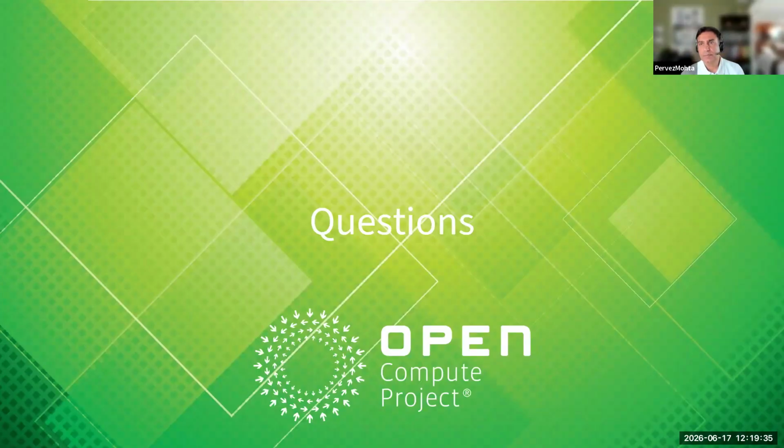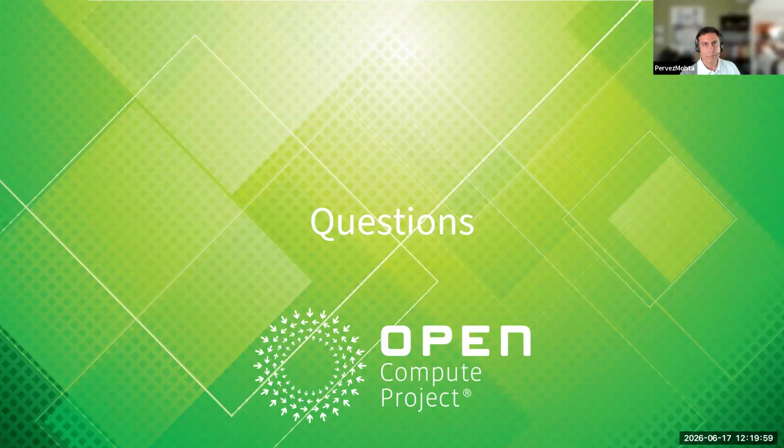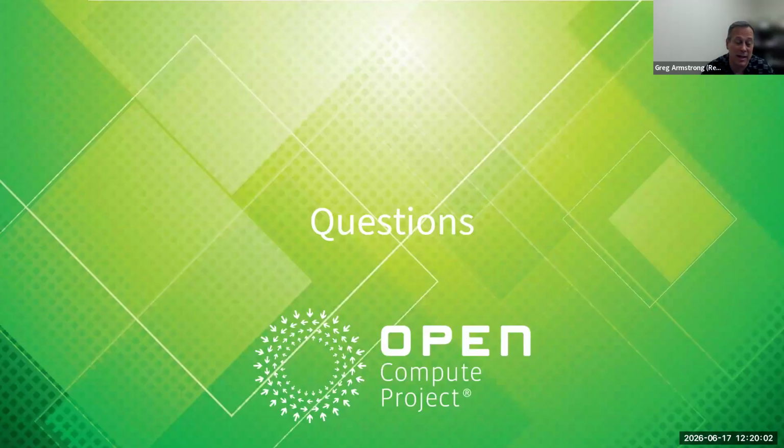Got it. So in a way, I think that's why 10 megahertz became popular. But we've seen 25 megahertz used, especially in some backplane applications. And maybe there'll be a switch to 25 meg because it's probably a more common clock frequency used in cloud servers, or it may even go to 100 megahertz. And as was highlighted, why not start modulating the PCIe 100 megahertz clock itself? We dabbled with that a few years back. But the big thing is you get some pushback, because sometimes that 100 megahertz is used directly as the clock, so manipulating the duty cycle is not good.